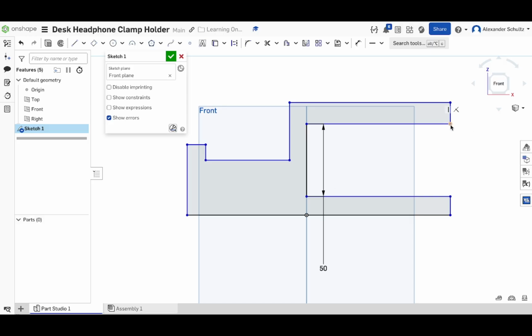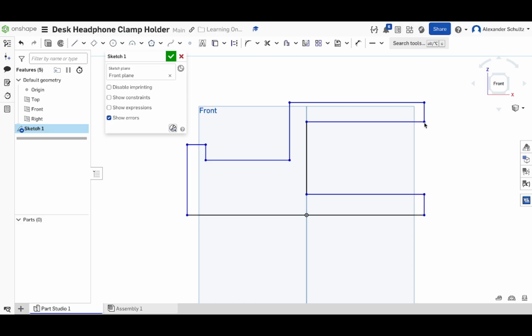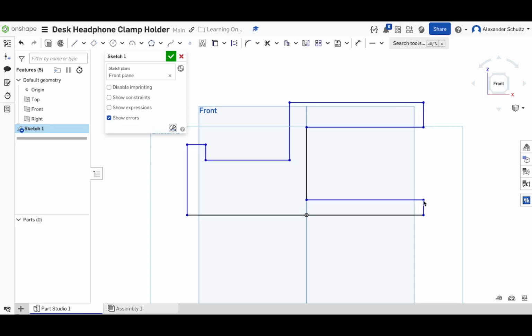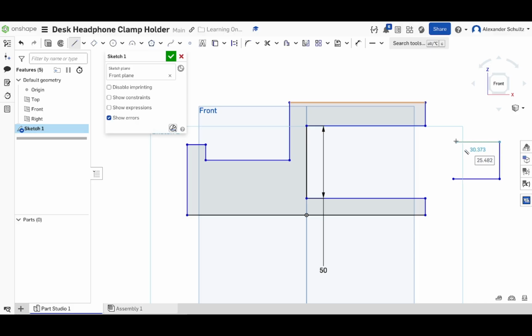So you can see here also, I'm not sure if you could tell, when I was dragging this point, this line also moves in. That's because when I was drawing this out, vertical constraint was automatically applied. So if I'm drawing a shape like this and I go like this, if it doesn't work at first, you can hover over that point and then drag upwards, and then you can see the horizontal constraint is automatically applied, and the vertical constraint was applied.